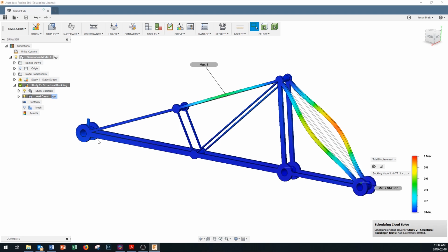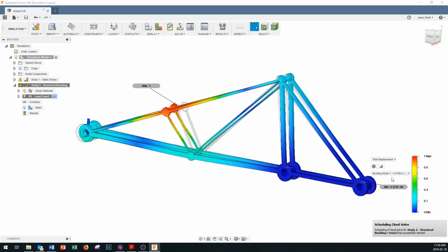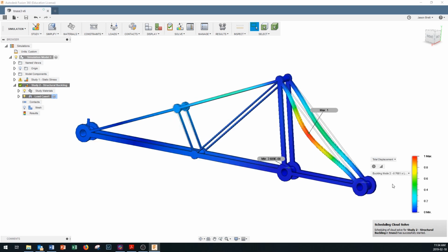What that means is that if we reverse the direction of the load, those ones are going to buckle. I don't see any positive buckling load factors in here. So I think we've stiffened this structure up to the point where it should survive. We could do different buckling modes and let the computer figure all that out, but I think we've got this structure pretty rigid.